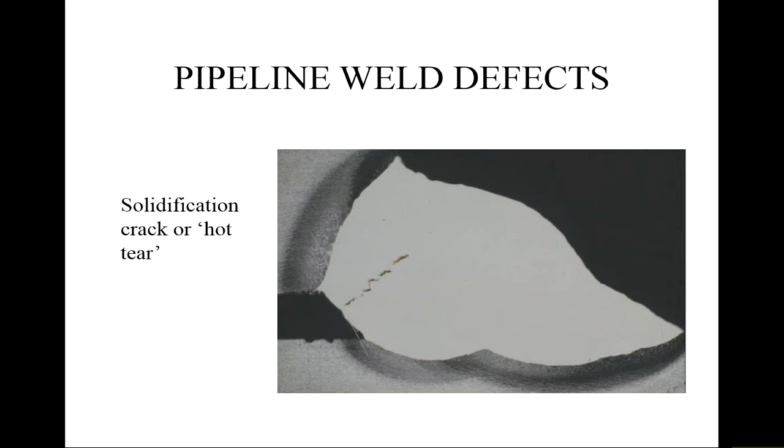But this contraction might differ as a function of the phases present in the weld, and it also depends on the ratio between the width of the root pass and the depth of the root pass. So the larger the ratio between the depth and width, the higher the possibility to have a crack that is caused by solidification.